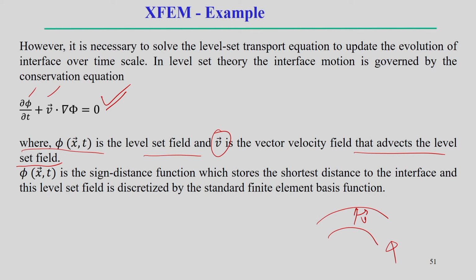This level set field is discretized using the standard finite element basis functions. With the standard finite element basis function, we can discretize the domain and solve this equation for this particular field, and that field defines the actual interface in terms of the shortest distance to the interface. It stores the data in such a way.